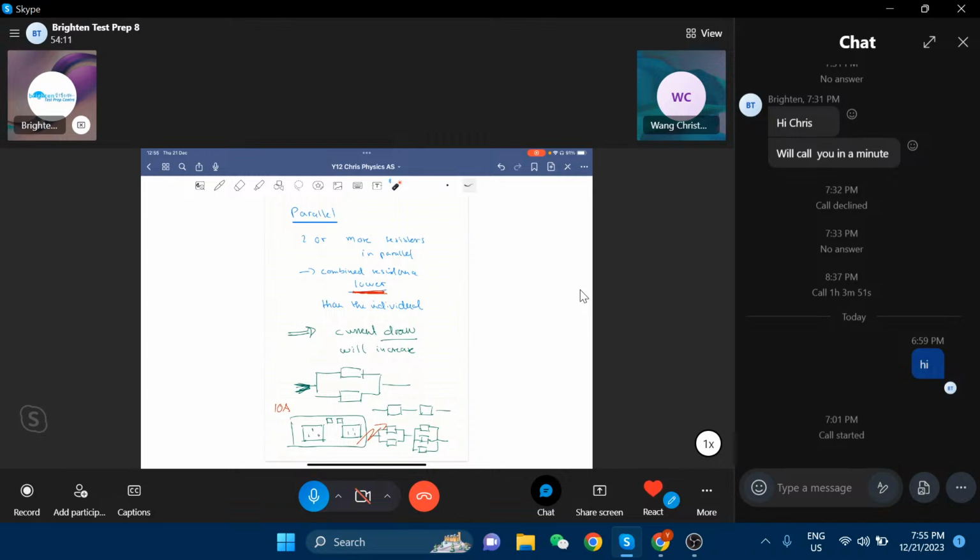And if you now start to multiply that stuff, you suddenly have maybe 10 amps on one. And if you repeat the same on the other one, because it's a room where two people are working and they plug in wherever they can, and each one has their own devices, suddenly they start to draw maybe 20 amps. Or maybe just with this one alone, already 12 amps. What will happen if it's properly wired, Chris? If I draw too much, say I draw 12 amps through that 10 amp fuse? The fuse will blow. Yeah, exactly right.